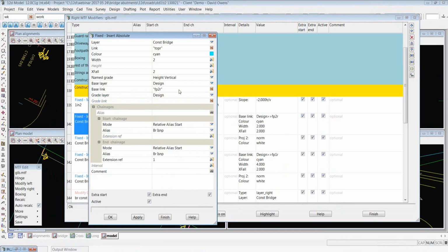In this case, I actually had curb and channel and footpath. It wasn't just a shoulder like a rural road. It's a more urban kind of environment. And I just extended it out a little bit of width, with the normal standard footpath crossfall. You'll see the length that I'm constructing is only 1 metre long. I've just created an alias that says the bridge inspection platform takes a certain distance along my road, and in this case, it is only 1 metre long.